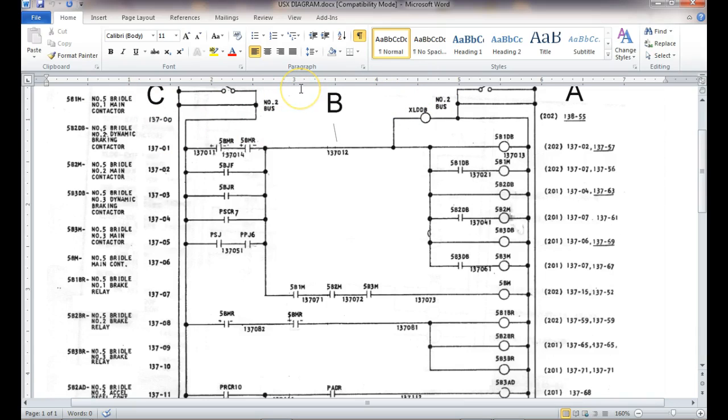So if you put a comment on the rung, it goes above the rung. If you put a comment about the coil, I think it goes above the coil. What RS Logix does, it'll display symbols, which Siemens calls tags, by the way. It displays those in green, and then it displays comments in yellow, with a yellow background.